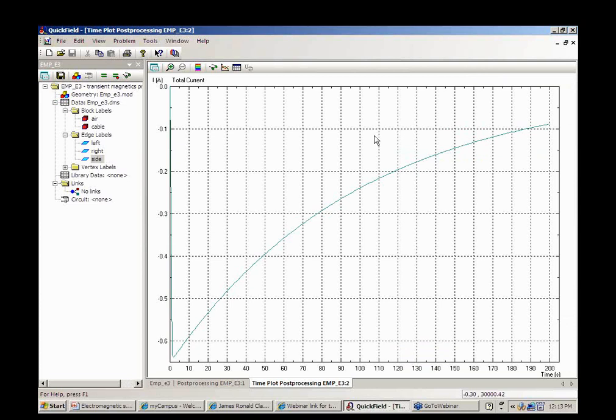Okay. This is in amperes. It reaches about 1 ampere, or actually 1/2 ampere, and then it kind of dies off as the Earth's magnetic field is going back into its normal configuration here. So this is a 300 meter cable, so if we're going to much larger cables, the surge could be even greater here, and it could be quite substantial as far as damage.